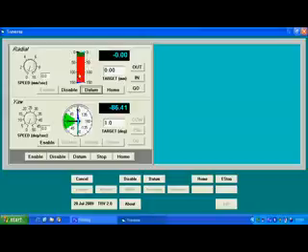To move it in, we can set a speed, and I'm going to set a speed of about 4 millimeters a second. We can go up to 5 millimeters a second. That's a reasonable maximum for this particular actuator. We can try and go quicker, but there's a potential then that the motors will stall because they lose power. We have an in and an out button, which are manual buttons, and it will move in providing the button's pressed. So if I press the button, it starts moving in. Release it and it stops.